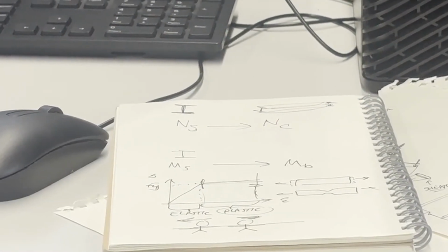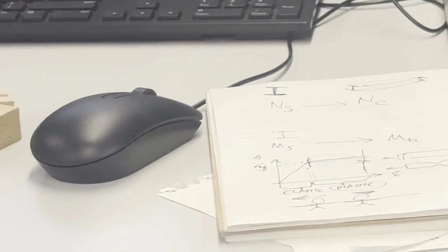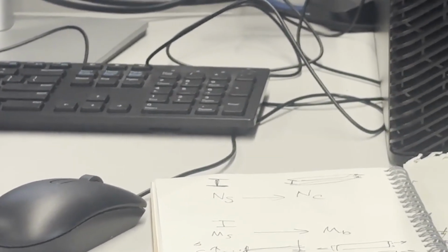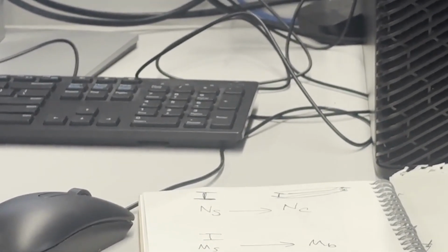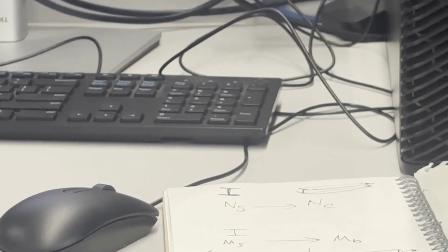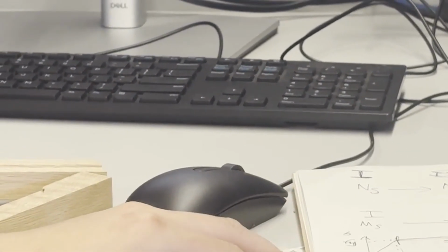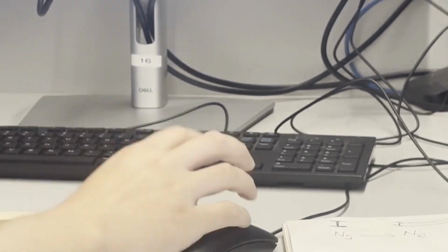But what happens is, at that yield point, you don't need to put in any more force in order for this kind of cheese stringy effect to happen, right? As long as you apply a constant force, it's going to keep elongating. So that's a failure mode that happens in steel beams, right? Here I've drawn it in tension because it's easy to understand, but it happens in bending as well. Okay, so back to bending.